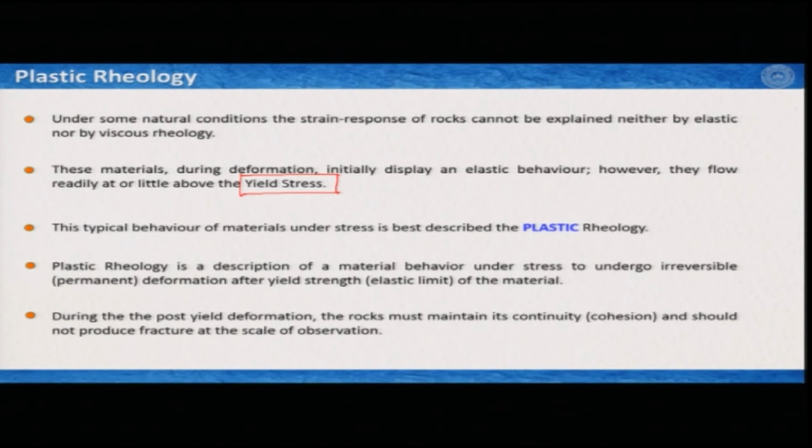So, yield strength is the limit of your elasticity. After you reach the yield stress, you cross your elastic limit and the elastic property of the material is gone. You cannot bring it back to its original position. Whatever happens after that is not elastic deformation.